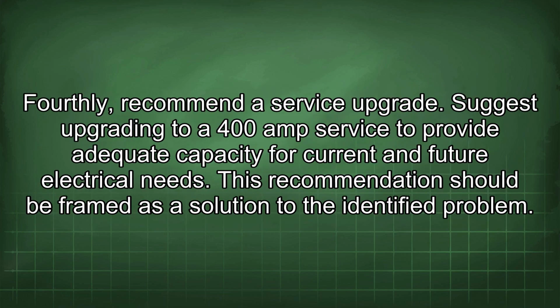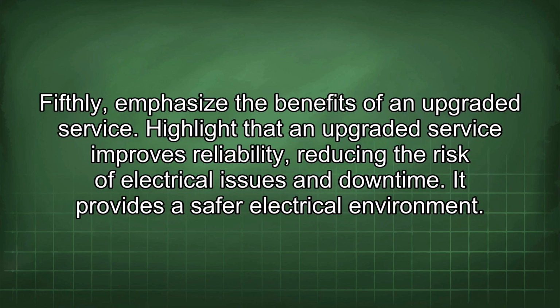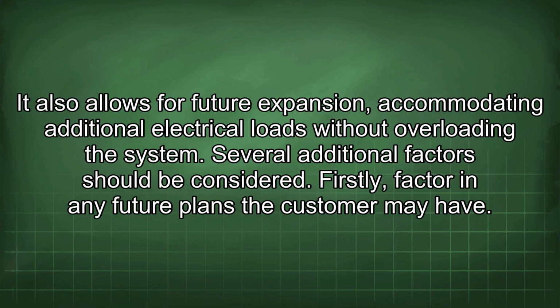Fourthly, recommend a service upgrade. Suggest upgrading to a 400 amp service to provide adequate capacity for current and future electrical needs. This recommendation should be framed as a solution to the identified problem. Fifthly, emphasize the benefits of an upgraded service. Highlight that an upgraded service improves reliability, reducing the risk of electrical issues and downtime. It provides a safer electrical environment. It also allows for future expansion, accommodating additional electrical loads without overloading the system.